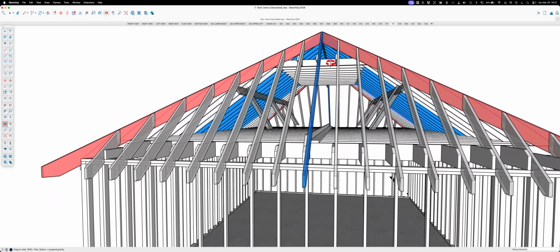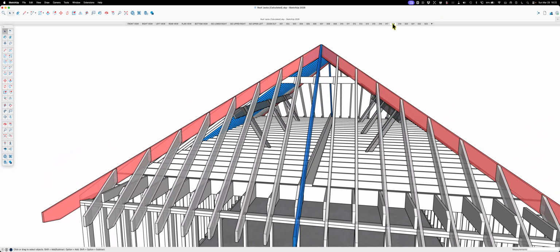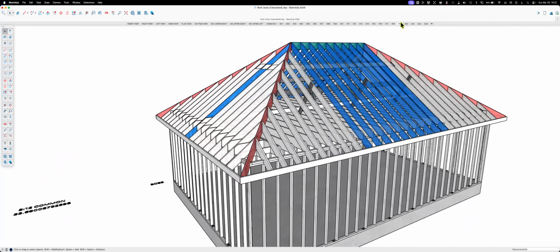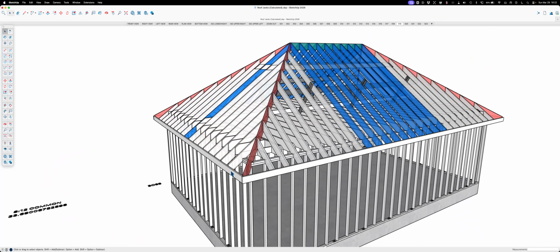So this is a pretty stout little building so far. And then I put the subfascia out here, playing down to the outside edge of the subfascia, and then whatever you're going to use, like we use a lot of 5/4 up here, but whatever you got in your region.